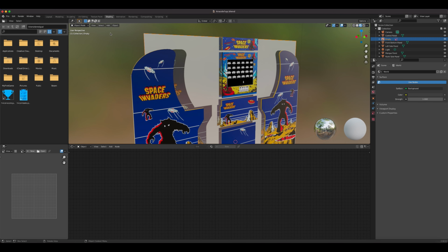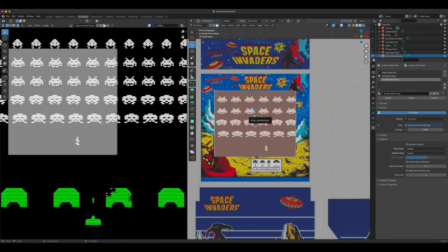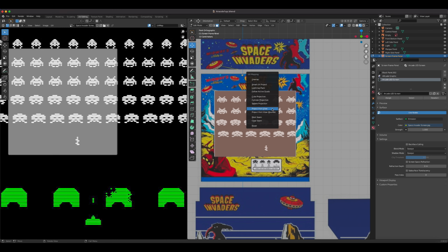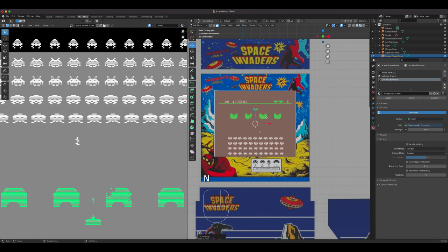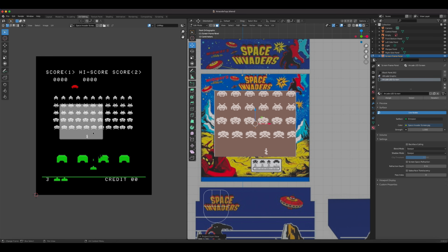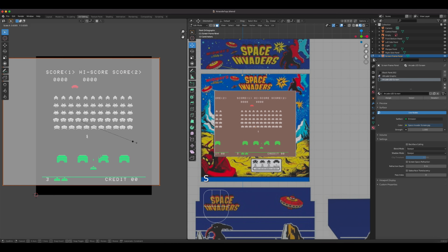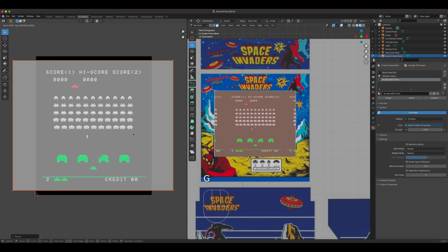and there it is on our screen. Let's go back to UV editing, select this one, and then I'm gonna go project from view, press U. Let's turn on screencast again. All right, press U to unwrap, project from view. There it is, and I simply press A to select everything here, and then show the screen like so. Kind of center that. Let me do some scaling.